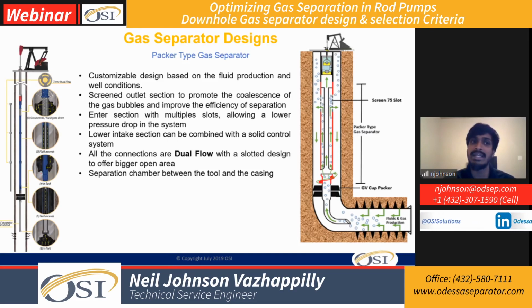When the fluid exits at this point, since this is the outlet section, having screens with a really big open area, or a slot size opened up enough, lets the smaller gas bubbles released inside this gas separator coalesce and get bigger. Like Carlos mentioned before, the buoyancy effect is higher for these bigger gas bubbles, so it helps in separating the gas bubbles much more easily compared to smaller ones.